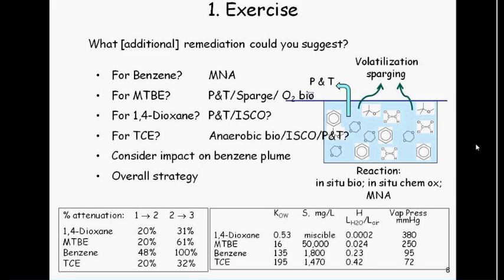So there's an example of how, in a very simplistic way, you can very quickly sort through the chemical issues and get a very quick handle on what might work and what certainly won't work. That's just using the environmental property. So, like you mentioned, if you do something to reduce the concentrations before pump and treat, does that greatly affect the cost of the pump and treat, or is it not worth it to do a first step to reduce concentration? So would reducing concentrations help?